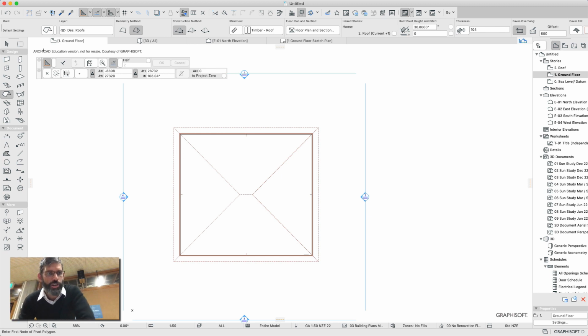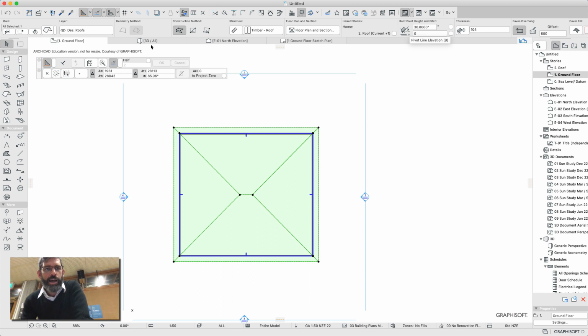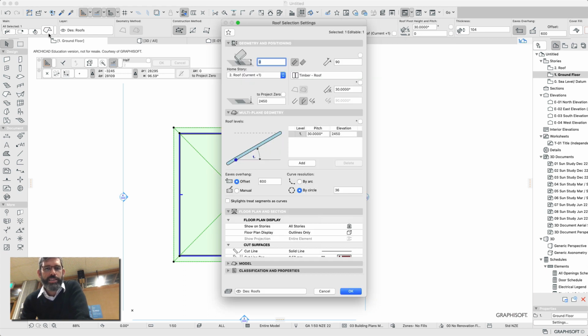Now, actually, I should have specified the height, which I didn't. So I'm going to select it. Now, how long? I think our walls were 10 meters high. If we go to its settings, it's actually being attached to the roof, which, if we were using ArchiCAD correctly and doing all these things on different layers, would make complete sense. But you guys might end up with lots of buildings with lots of roofs at different heights, so it's not going to make much sense at this stage.